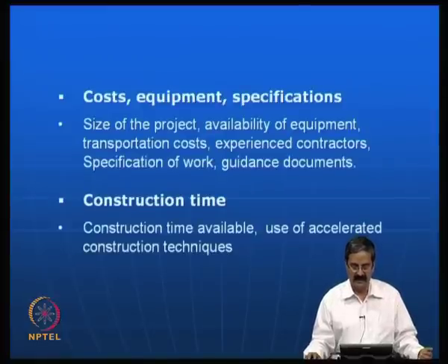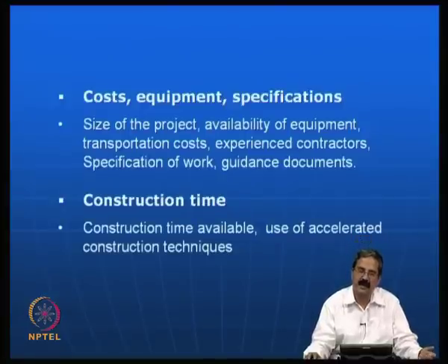Many of the ground improvement techniques need specialized contractors. It is not easy, because in soil mechanics or geotechnical engineering you need a lot of experience in soils, otherwise the project will be in serious problem. I must tell you many examples in our own case: soil nailing, you do not have good contractors; micropiling, you do not have good contractors; but if you have good contractors, they are very expensive. So, the owner is always worried about whether to go for a contractor who can give a low price but with uncertain quality, or go for a good contractor where we are assured of the quality, but at the same time he is expensive.